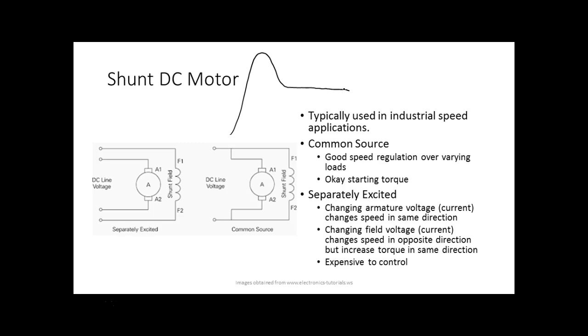So a shunt motor is going to try to, and if it tries to slow down, the armature is going to try to slow down, which causes the counter EMF to go down, which has caused the current in the armature to go up, right? You understand, which causes the torque to go up, and it'll come up to the right speed.